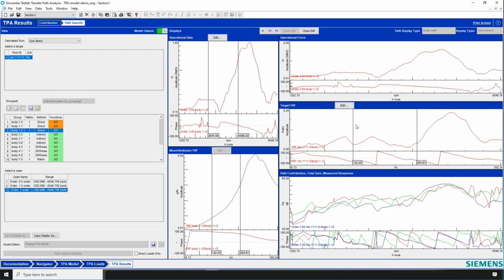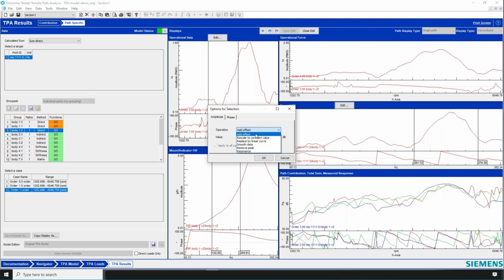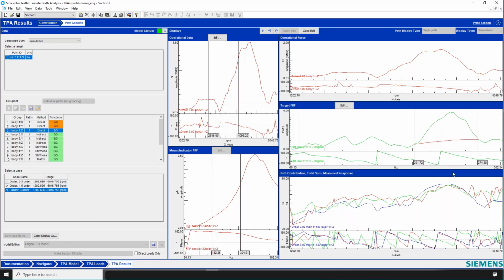TPA also lets you do some other things, like you can come here and say, all right, structural people, if you could reduce that sensitivity of your structure by 90%, what would the new sound level be? And you can see if it would even be acceptable. Maybe it's not realistic per se, but if you could reduce it 90%, would you even get to the dB level you think you need to be at that operator location in order to achieve the results that you want?